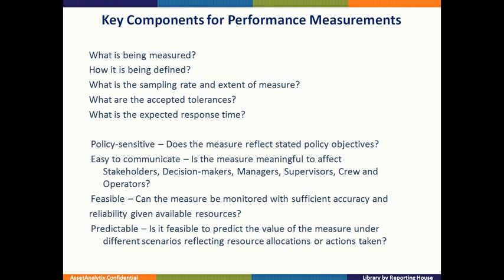Then in some cases, we have to determine whether that KPI is feasible to generate. In the case of MTBF, it could be very difficult if the correct data is not taken into account. So many times, a CMMS system may not actually record the time the asset went down.